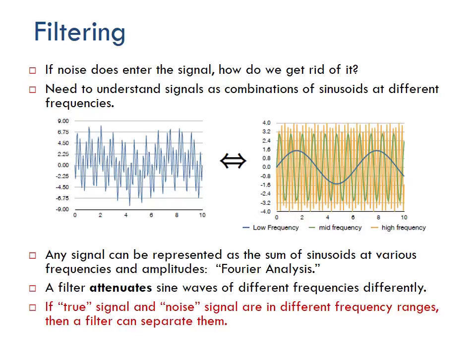So there's a lot of cool stuff you can do with sound in this, and I'd encourage you to try to test some of these out on your op amps. So your MyDAC is capable of outputting different frequencies. So output some frequencies, listen to them from your op amp, and then try to clean up the signal. Put a low pass filter on there. So how does it sound? Put a high pass filter on there.